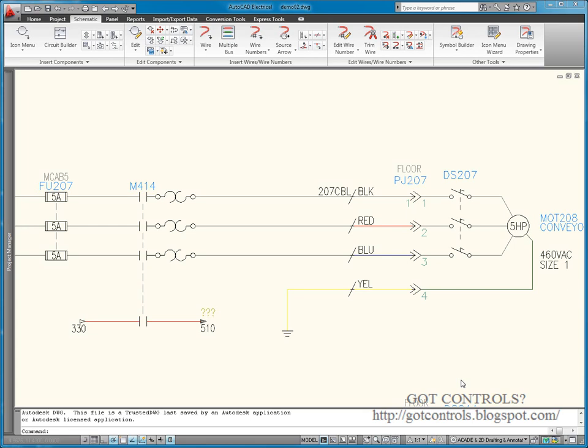Okay, now we're going to take a quick look at creating associations between terminals when inserting new terminals into new or existing drawings. So this is when you're dealing with new terminals. In a later post, I'll show you quick and easy ways to deal with existing terminals that you may have created in previous drawing sets before the multi-level terminal functionality was introduced into AutoCAD Electrical.